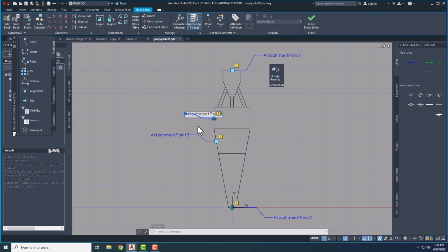The order with which you do these has a little bit of effect. AutoCAD, when it's doing its validation thing, that is a little complicated and you may not end up using, tries to direct, especially if they're headed in one direction, like one is going straight down into 2, it tries to connect the pipeline coming in from 1 to 2, and then 3 to 4, and 5 to 6, and so on. Doesn't always work out, but if you can just put them in the correct directions like that, it can help AutoCAD out a little bit. That's all we need to do. Make sure you do name them these. Otherwise, you won't get that circle with the crosshair connection point for your block.